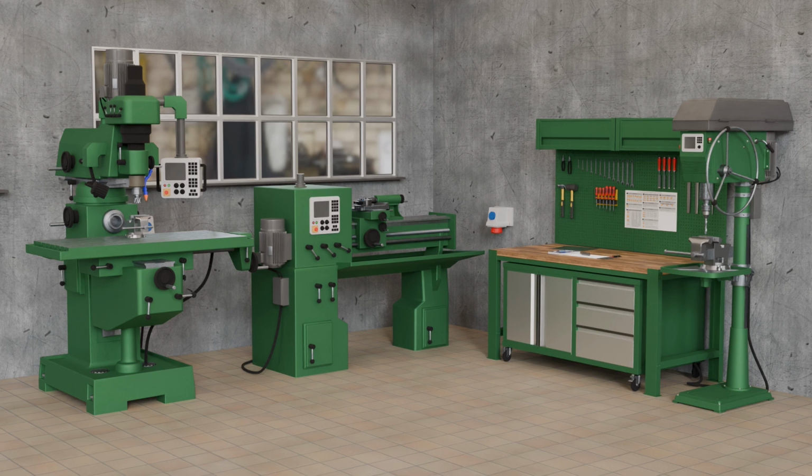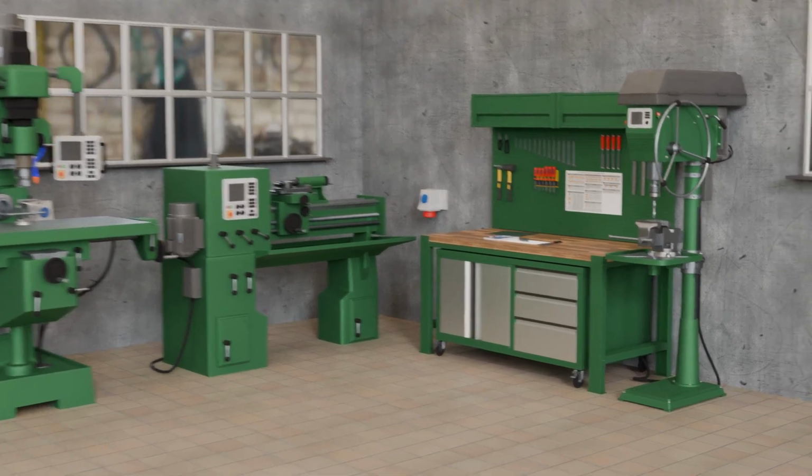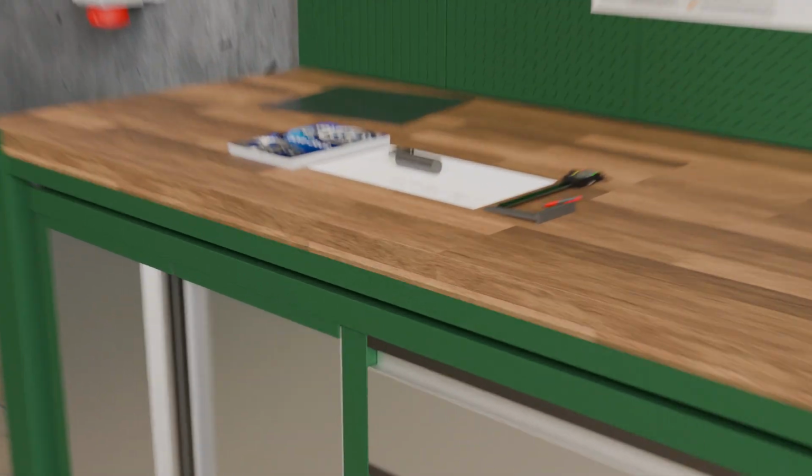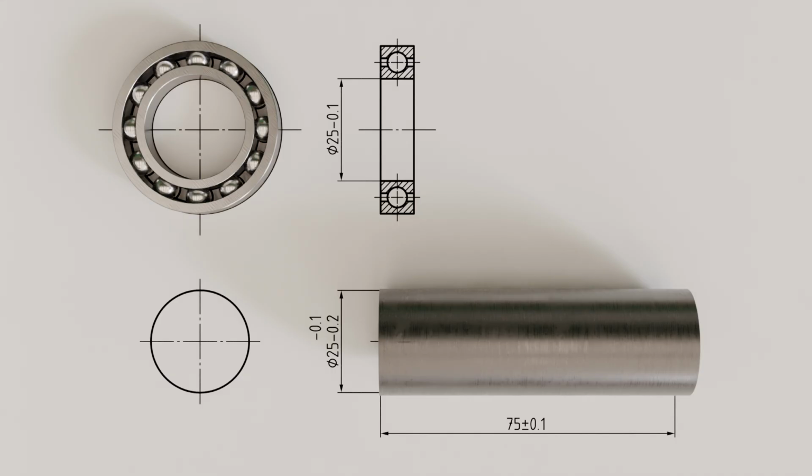In the linked video, we have already explained the necessity of specifying tolerances in detail. These tolerances referred exclusively to dimensional specifications, so that in this context they are also called dimensional tolerances. Dimensional tolerances generally describe the permissible deviations of a dimension. Their purpose is to ensure the function of components.